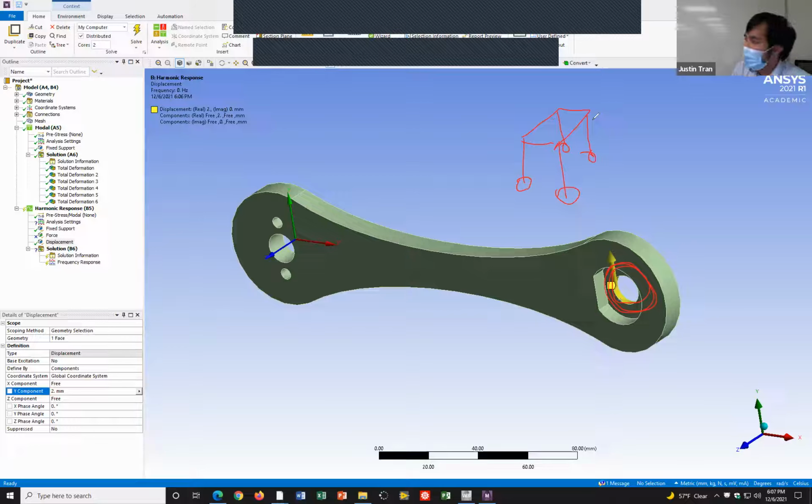Which is not what we want, right? So what we want instead is to see how the system naturally responds to external effects. If you are going to do an oscillatory displacement on the building, you can apply the oscillatory displacement on the bottoms, but then when you measure the frequency response, do it on one of the first floor platforms or the second floor platforms. That way they're far away from the displacement boundary conditions.